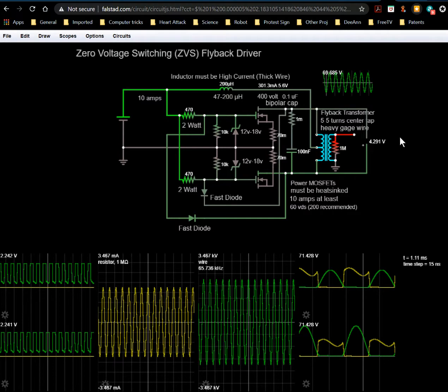They actually are back-to-back electrolytics. Although there may be a little more magic to it, like resistors in series with it that help level out those voltages. But generally speaking, that is a way of creating a large value AC capacitor, though it will affect your capacitance.